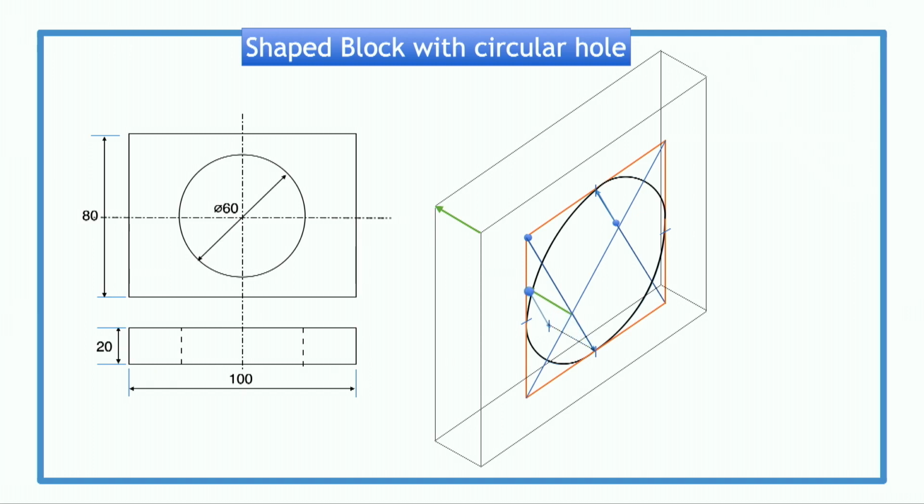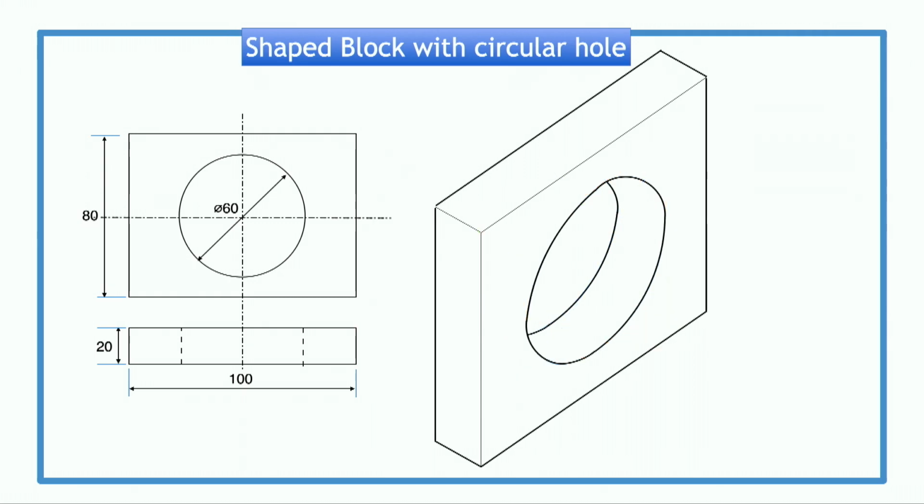For the next part, we mark the offset distance, as well as the contact point on the vertical side of the crate, and draw in the back arc. The last part is offset and drawn in. The outline is added. This is our completed block, which we can render to give this.